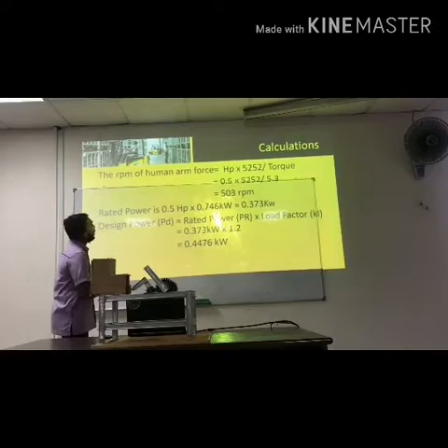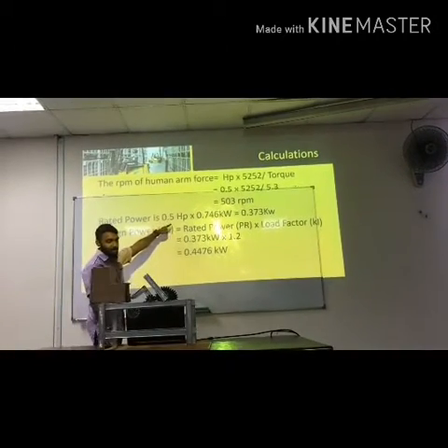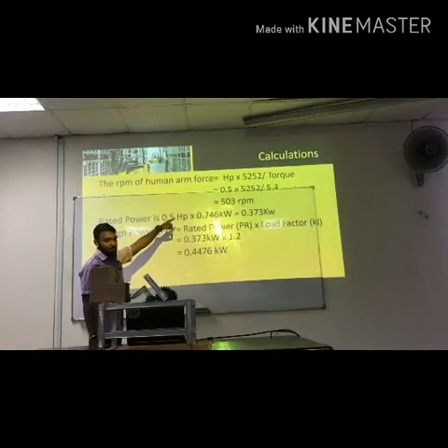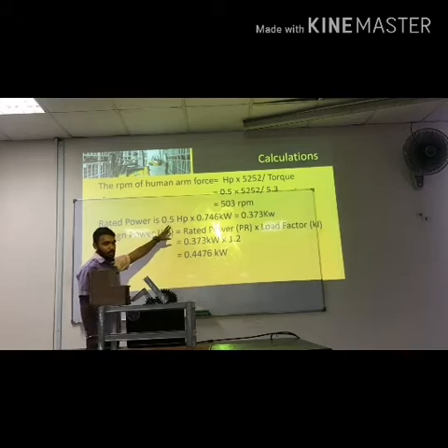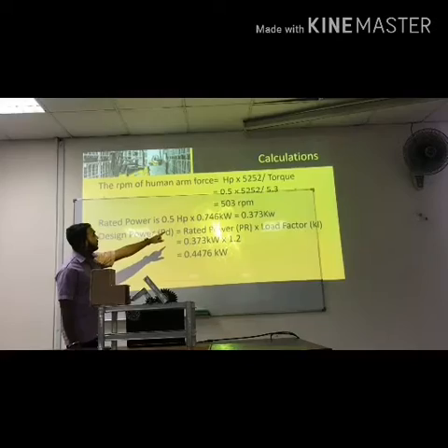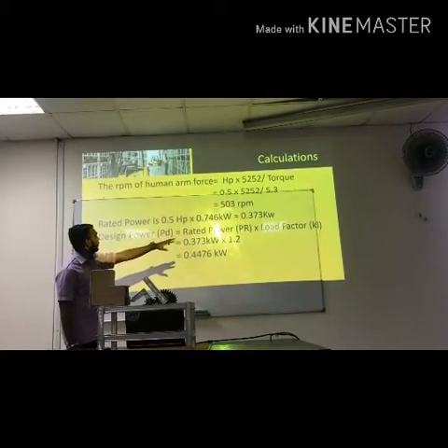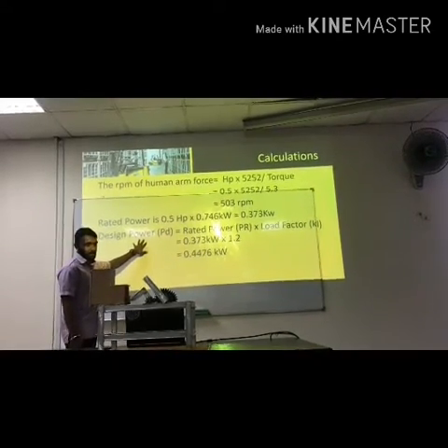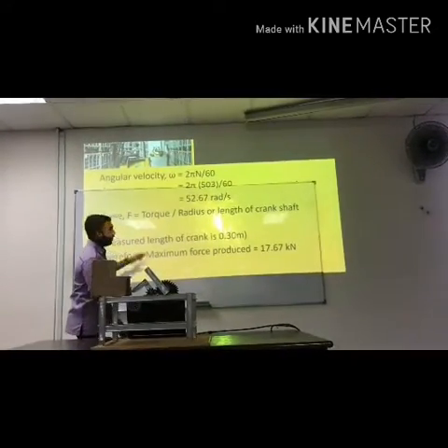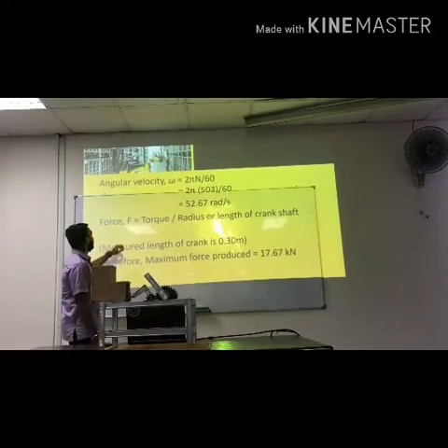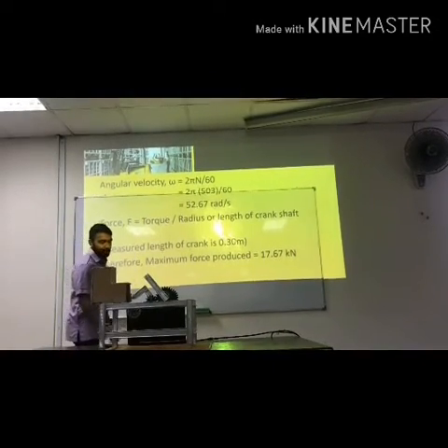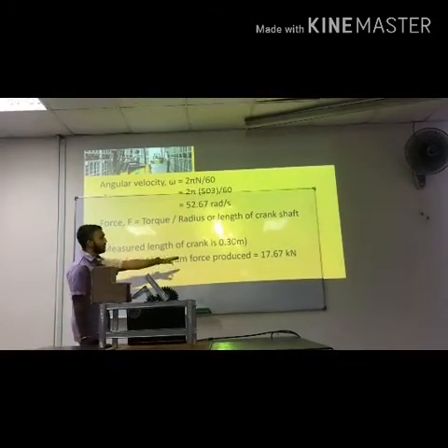So for the RPM of human arm force, we have the calculation 0.5 times 5,225, then divided by 5.3, and you get the RPM of human force. Then the rated power is 0.5 times 0.746, equal to 0.373. For the design power, we get a total of 0.4476 kilowatt. The angular velocity we get is 52.67. We calculate the force, which is torque divided by radius length, and therefore the maximum force produced is 17.67.